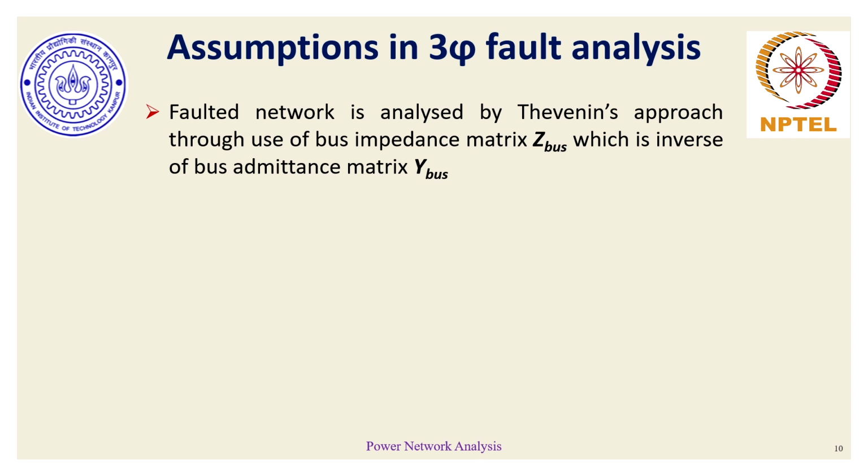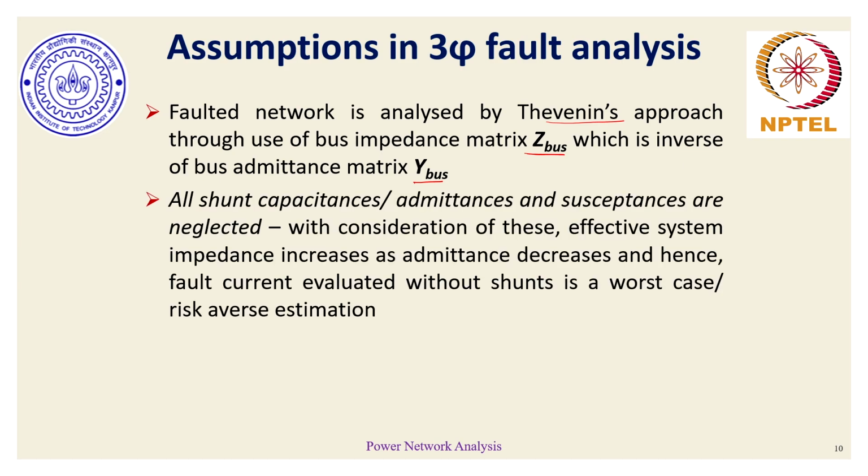We'll start with the three-phase faults first. So our faulted network, we will analyze it through Thevenin's theorem, and while applying Thevenin's theorem, we would extensively make use of the Z-bus matrix, which would depend on what is the Y-bus matrix. The evaluation of Y-bus remains the same as we discussed earlier in the power flow analysis module.